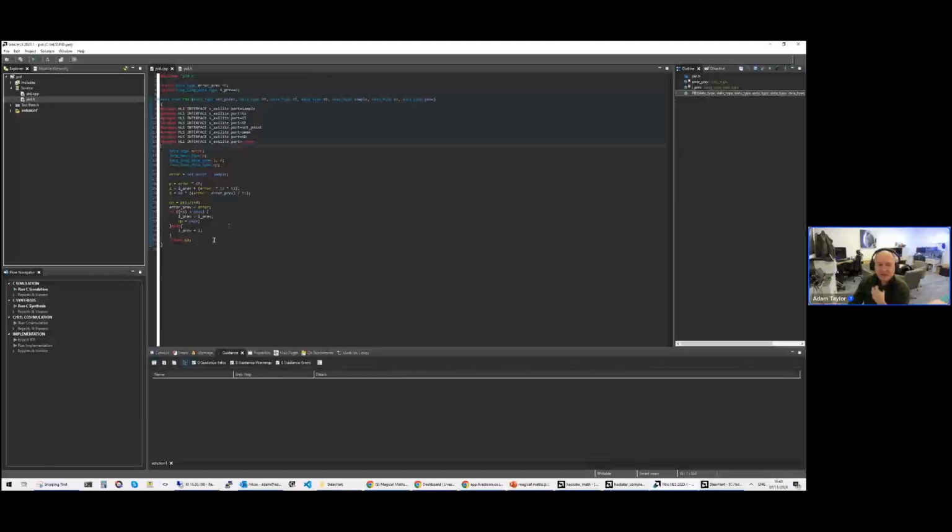We're just running through and doing a standard PID algorithm. So we're doing the multiplications, the addition, and then we're limiting the output power depending upon the calculated value. This is all nice and simple, where it's just this multiplied by this.